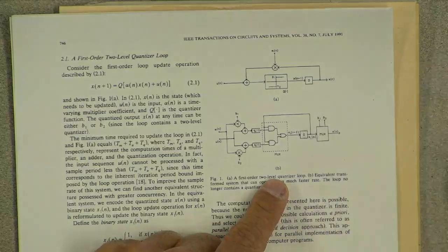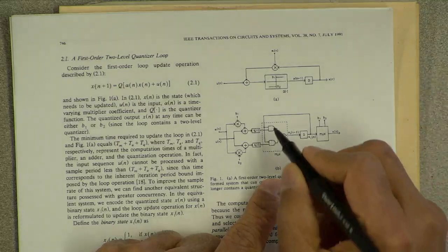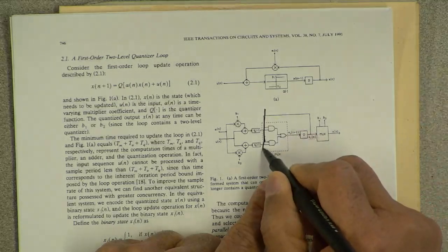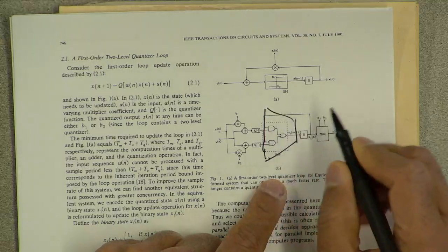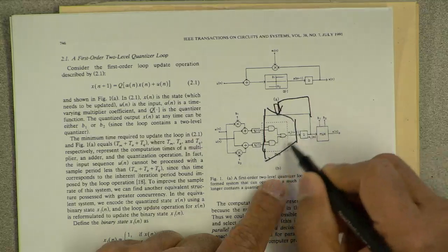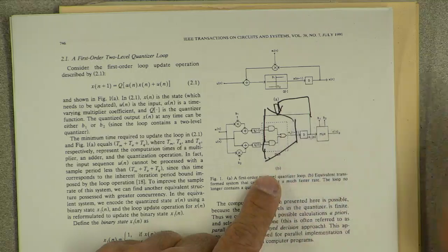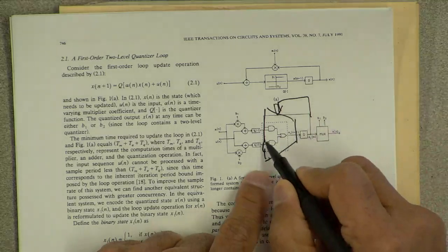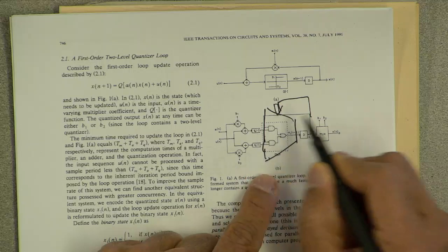So we now have a binary variable x1n. X1n is binary that takes 0 or 1 value. So think about this as a 2-to-1 multiplexer. And if that x1n is used now as a control signal, what you see here is that the two AND gates and the OR gate is simply a multiplexer. And so we have pre-computed the quantized values.